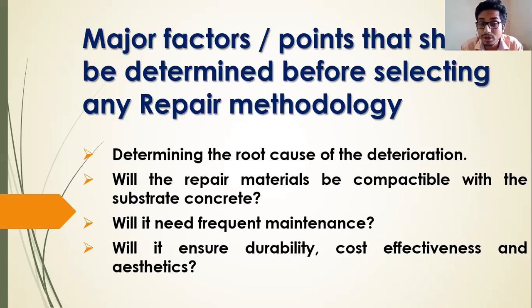So we should determine the root cause, and we should adopt some precautions to stop that root cause which is causing the deterioration of the concrete structure. So determining the root cause is very important in the case of repair work.